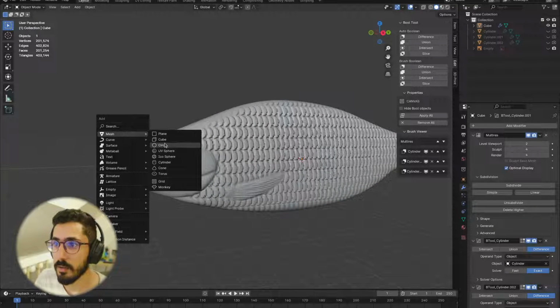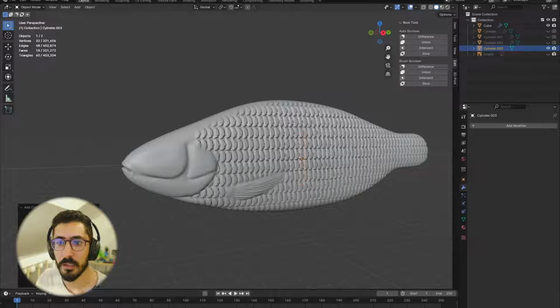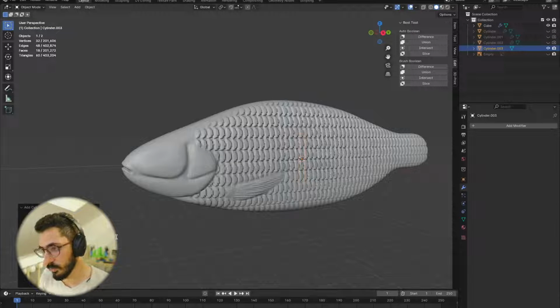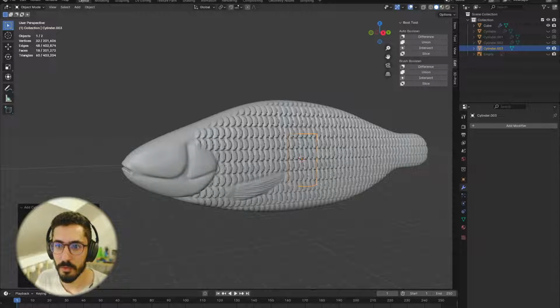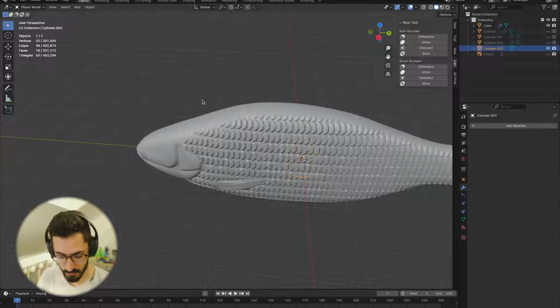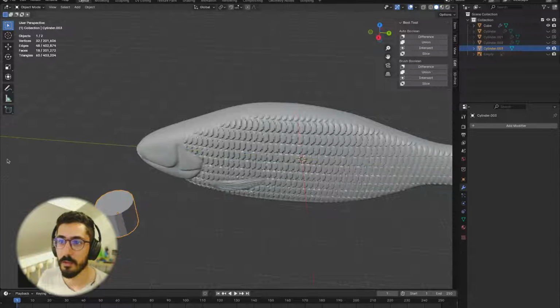Again, I'm gonna add a cylinder. I have 8 mil eyes. The radius is gonna be 4, and I want half a mil of clearance, so let's do 4.2. 4.2 is fine as a radius. Depth, we don't want it that big. Let's do 7. Where is it? Cylinder 3. Okay. No. Move it everywhere except the Z. Shift Z.